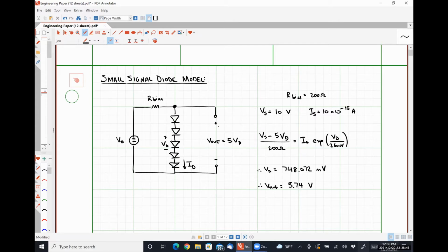All right. So this circuit is what is called a voltage regulator circuit, okay? So what a voltage regulator circuit does is it provides an output voltage that is supposed to be independent of fluctuations in the power supply voltage, as well as independent of what load is connected to, okay? So what we're going to do is we're going to increase our supply voltage by 10% and see what change in the output we observe, okay?